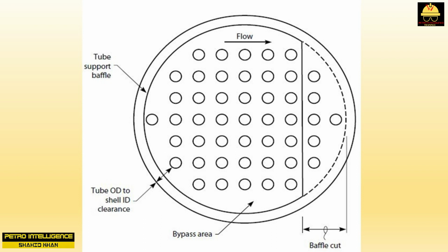For the seal strips to fulfill this function, one of the seal strips in each pair must extend the full length of the tube bundle. This is rather complicated to explain. However, if you look at a tube bundle that has been extracted from its shell, you will understand why this is needed, and how impingement plates render seal strips essential for good sensible heat transfer from a shell-side fluid.